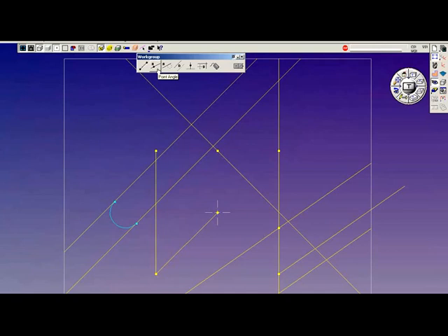Line, axis line. Axis line, as I previously mentioned, is the ability to generate vertical lines along the x-axis, horizontal lines along the y-axis. Vertical lines are placed along x, and I'm going to make my z value 0 because I always draw my geometry at z0 and do my depths with the tools.